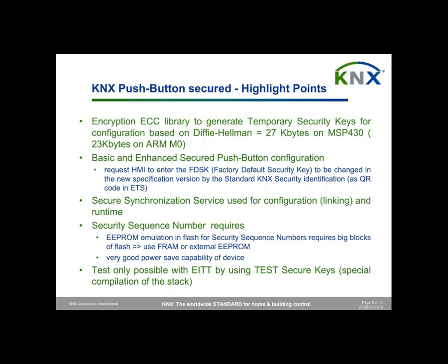KNX push-button secured. We have one specific part for security in push-button, which is the generation of security keys for making the configuration and also to generate runtime keys for security. And it is based on the ECDH, so elliptic curve Diffie-Hellman.